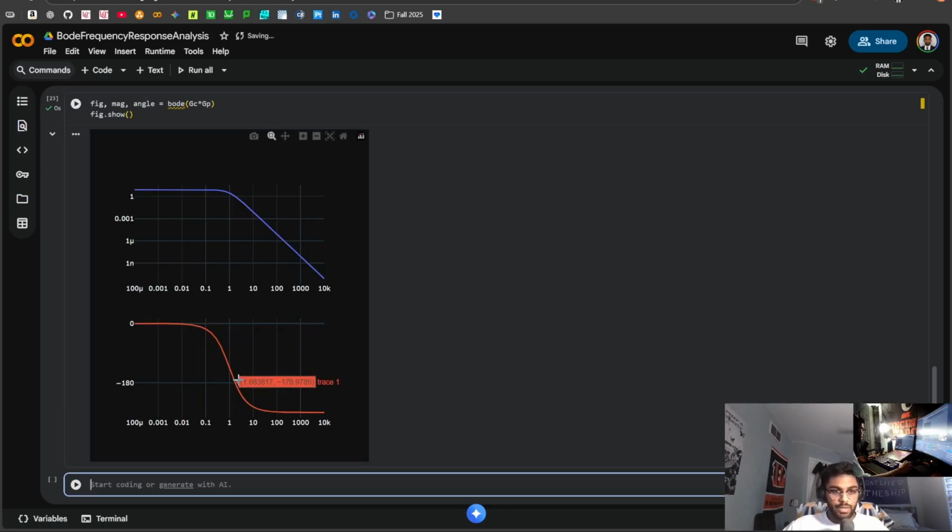So if we find our crossover frequency, about 1.82, yeah, we see that our estimate is around 0.89, so that falls just about under 1. We can probably use that as our ultimate gain.